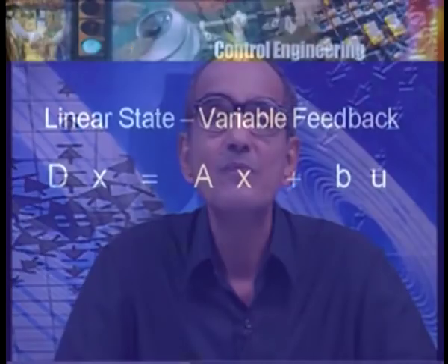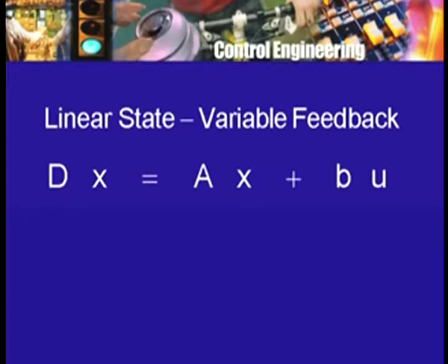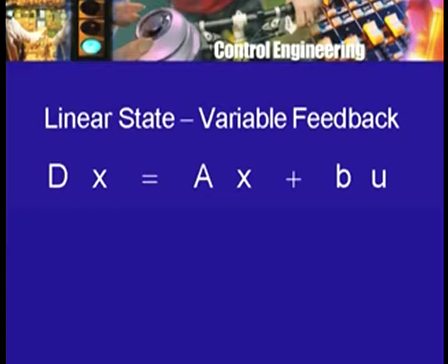For this purpose we want to use feedback. So, how shall we use feedback? Well, exactly the way we thought about it earlier. The input to the system u, instead of getting it directly, you obtain it as a combination of what is called a reference input and the feedback signal. So, in this case, this can be done and represented in matrix terms as follows. The input vector u will not be applied directly, but will be obtained from a reference input vector r.